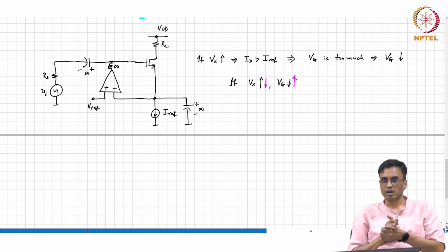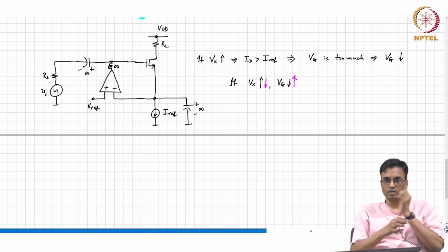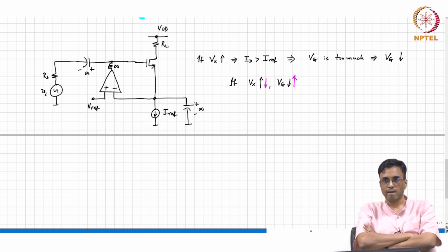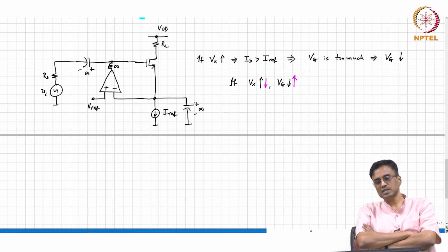Why is it 0? So if it is a voltage source, then if we change any resistance, voltage will not get affected. We change what resistance? Load resistance. Then the output shouldn't change. Okay. So then the only parameter you need to specify is the trans impedance. Okay. And what about a voltage controlled current source?